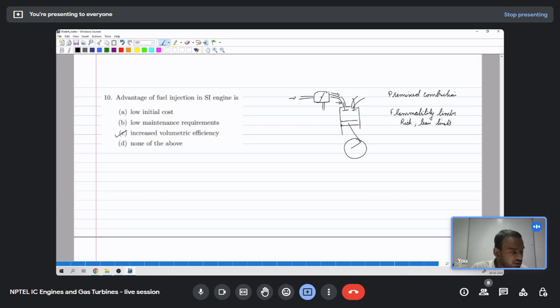Within this range only, the combustion can take place at a steady phase, or the fuel can participate in the combustion. If it is outside of this range, the fuel cannot even participate in the combustion. Because of this, we should always maintain the air fuel ratio of the engine to some limit. As we saw earlier, it is 8:1 to 18:1 for a gasoline engine.